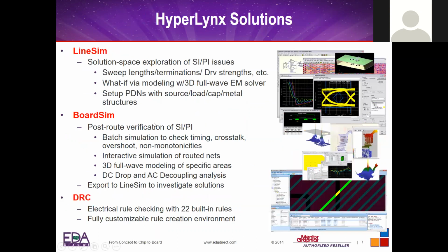Okay? Now, in terms of providing solutions to customers to deal with these issues, you can do a lot of analysis in pre-layout. Why is pre-layout analysis important? It is important because you can plan your stack up, you can plan your trace impedance. It allows you to pick and choose your chip vendor package. For example, if you have an FPGA, should I use this low cost version, or should I use a more expensive BGA type of package?